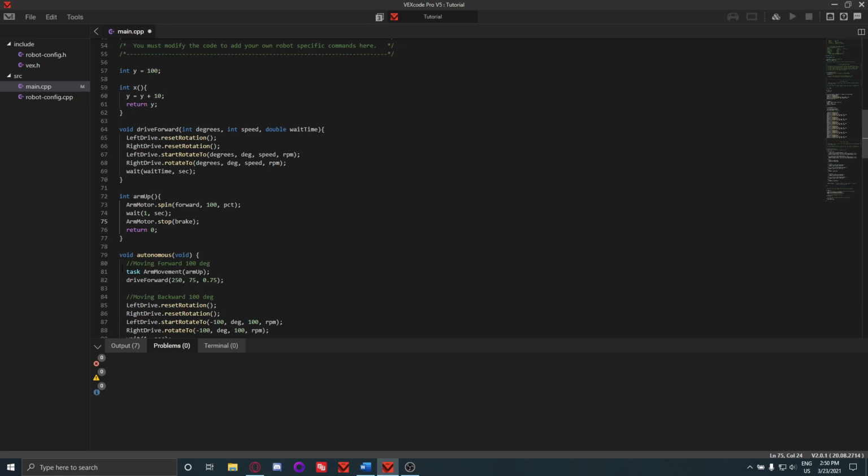You can use this task function to make a clock that runs in the background. If you want a temperature sensor, or a display that shows the temperatures of the motors, which I'll talk about more in the next video about sensors, this is useful for that as well. So anything that needs parallelization, you'll use tasks for.